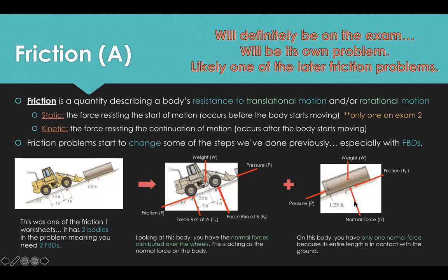So you have the normal force from the sum of the perpendicular forces, you have the friction force. Okay, and then you're given the mu sub s, right? Then you find the max friction, which is just mu sub s times the normal force. And then from there, you compare your friction value to the maximum friction value.